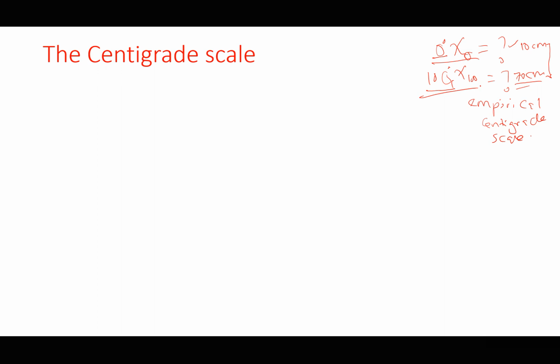the steam point is not 100 degrees Celsius. If the pressure changes, the boiling point or the steam point and the ice point may not still be the same. So there is nothing special about them. So remember, we have assumed that the property X varies linearly with the temperature, because we say the thermometric property is going to be assumed to vary linearly with temperature.